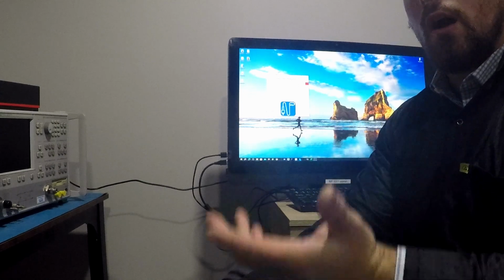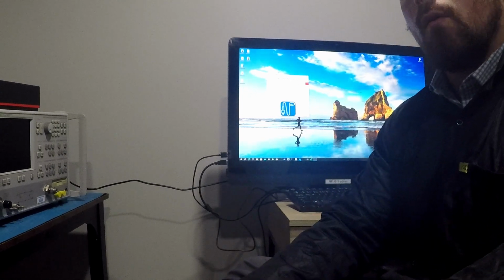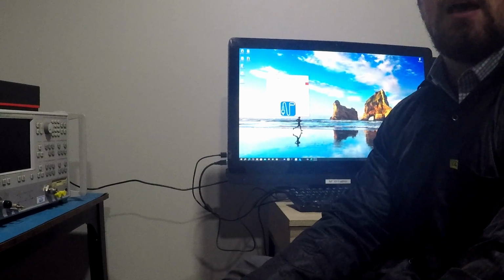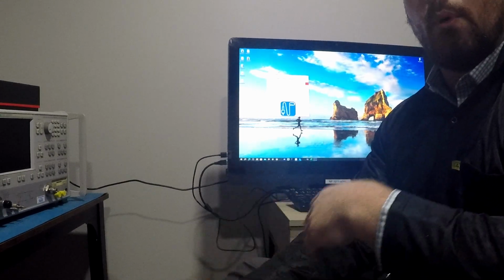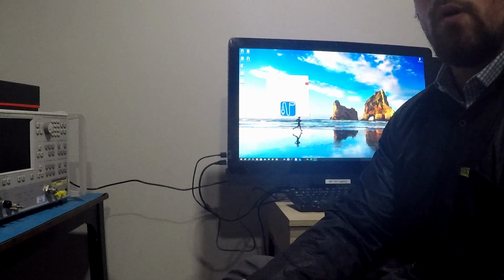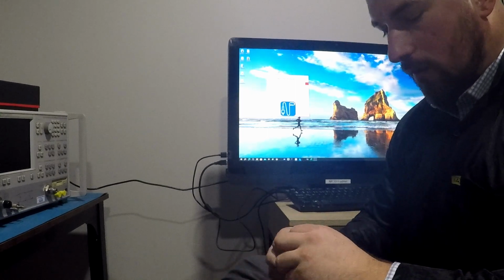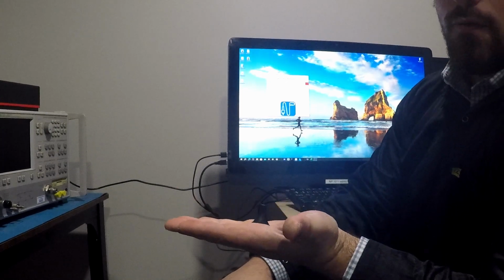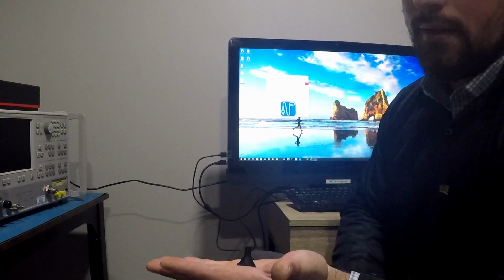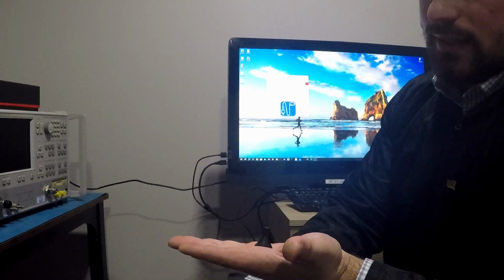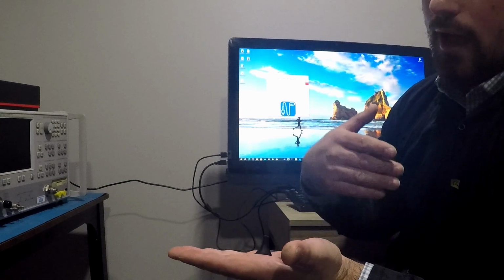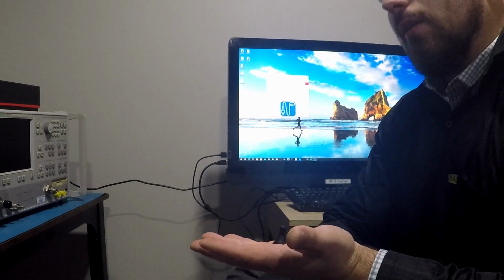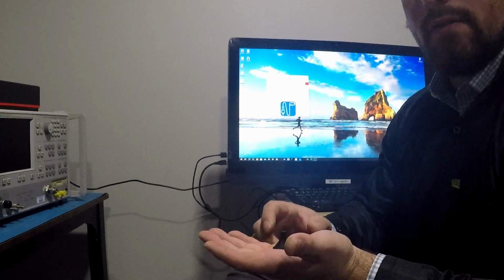It doesn't really show how powerful it is until you think about more complex 3D geometries where you have a lot of points to optimize. One of the things that really shows its power is this miniature horn antenna we had to solve for. It's about the size of a WR10 antenna, but it was optimized to operate from 12 to 27 gigahertz with about 8 to 10 dBi of gain.